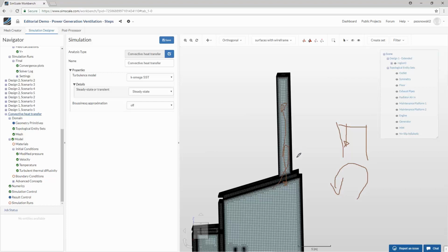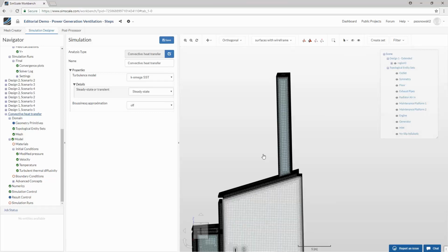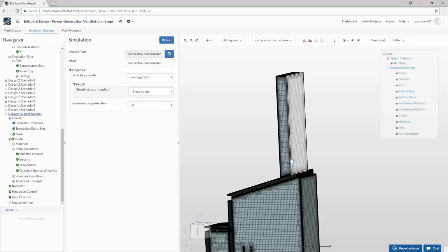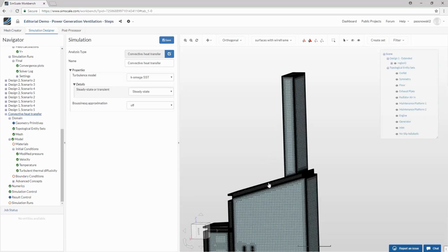In this case, I see that this has been done like 8 to 10 times the thickness of this object. But again, this really depends on what is the flow behavior that you expect in your system. So definitely extending the outlet is important. How long? It really depends. It might be that your simulation doesn't work because of this kind of backflow that comes from the outlet, and then you need to extend the outlet even further. Okay.